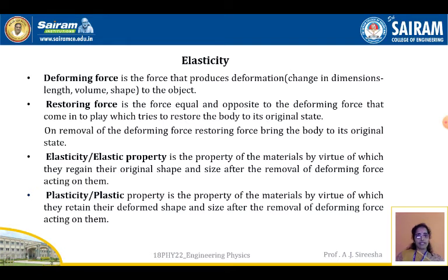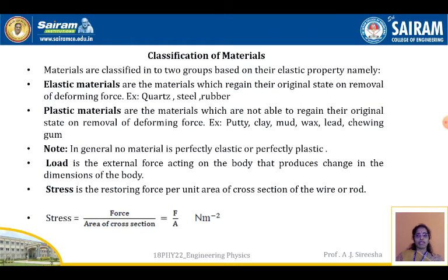Next is plasticity. Plasticity, or plastic property, is a property of a material by virtue of which it retains its deformed shape and size after the removal of the deforming force acting on it. If you look at plasticity and elasticity, plasticity means it is retaining. That means it is fixed. Once the body has changed its shape, it remains in that shape forever. Whereas elasticity means it is regaining, that is, coming back to the original shape and size after the removal of the deforming force.